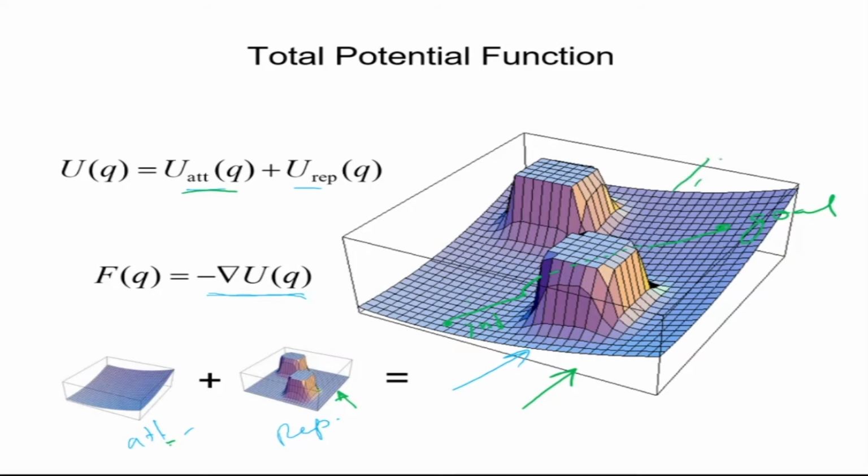Okay, so here if I draw it in top view, so this is my top view. So there is an obstacle here and there is one here. So if the goal was here and this is my initial point, then the robot will start going like this, then avoid, not so sharp, avoid like this, and then go to the goal. Okay, so it is going like this, then avoids like this, and then goes to the goal. Okay, so this is what we are seeing, how the attractive potential and the repulsive potential together affect the motion of the robot.